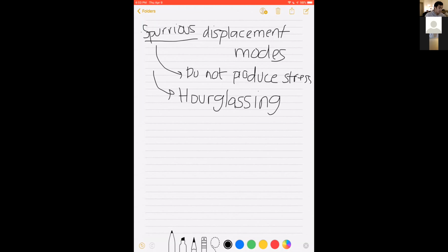Okay. And that energy was tracking, basically, some kind of spurious displacements that aren't realistic. So obviously we know when you're running dynamic simulations, you want these to be as low as possible. But if not, then you can do some things to correct it. Okay. Right, so the question is, why did these modes happen?